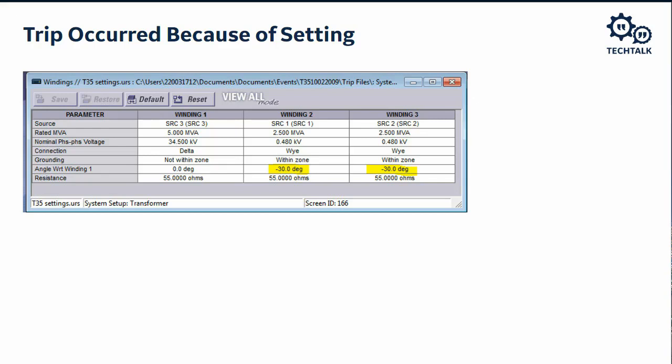So is this a problem? Well, it is a problem if we intend to parallel those transformers, if there's the possibility of paralleling those two transformers anywhere in the power system. If there is, that means that what we're calling A phase is really at a 60-degree angle to B phase. That looks more like phase to ground voltage appearing across what we think is A phase. That's a problem, a big problem. If we ever parallel those, there's going to be enough circulating current that it's going to damage equipment and probably damage these transformers. So if that's a problem, then we need to change the primary connections.